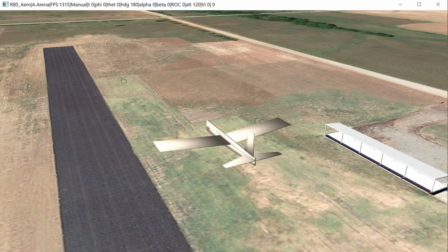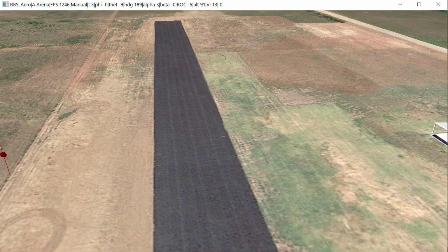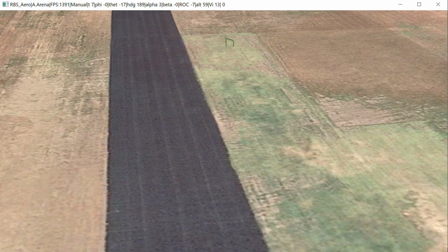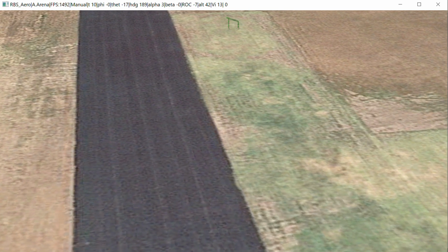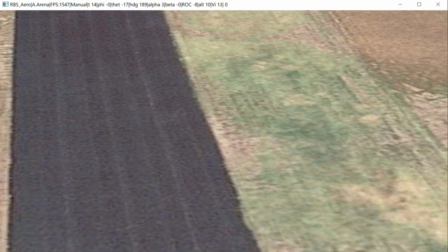And so it dives. It requires the airplane to dive and use the phugoid to pick up speed. So it's wasting, you see, look how much altitude it wastes, instead of using that altitude to glide. So if my goal was endurance or range, I could do much better than this.